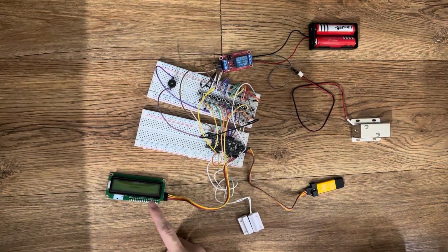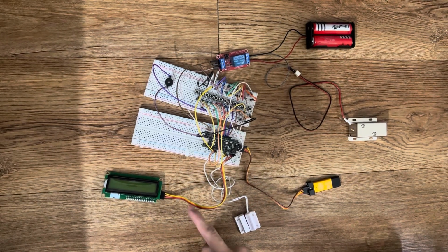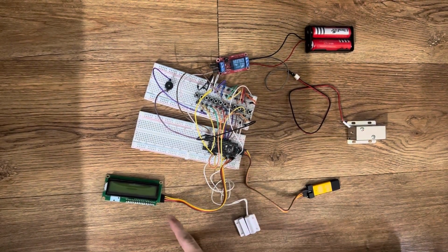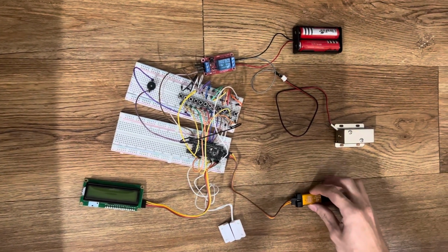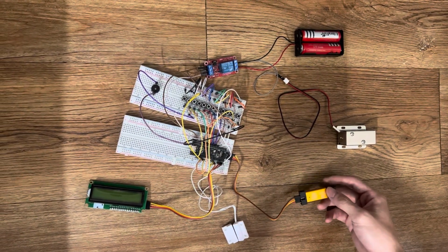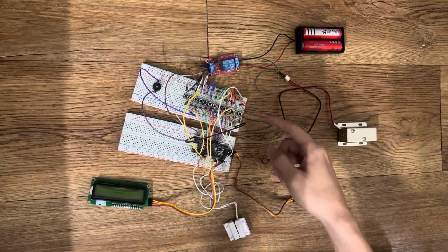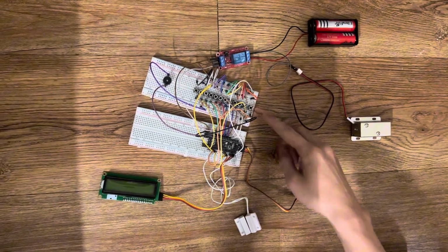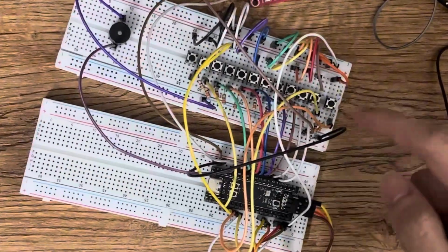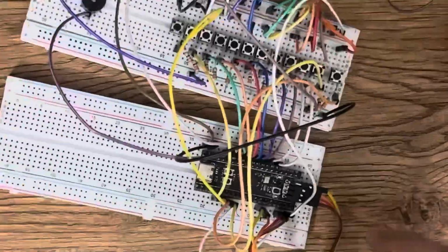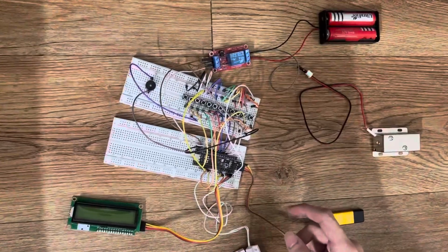The first one is the 16x2 LCD I2C, where the orange line is SDA, which connects to PB7, and the yellow is SCL, which connects to PB6. This is the black pill, which is connected to the power source. This is the USB connector, which we can connect to a computer. There are 12 input buttons here. The first one is the reset button, connected to PA10, and the second one is the enter button, connected to PA11. The remaining 9 buttons are connected to PA0 until PA9. Each of them is an active high push button with an external pull down resistor.